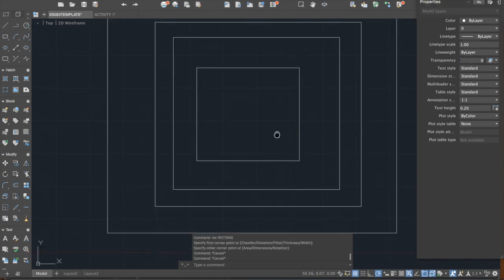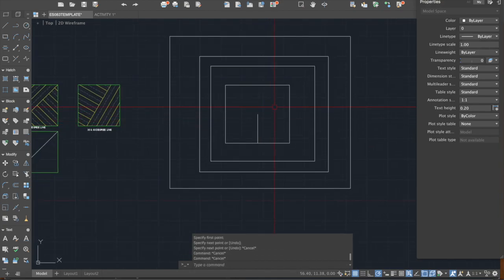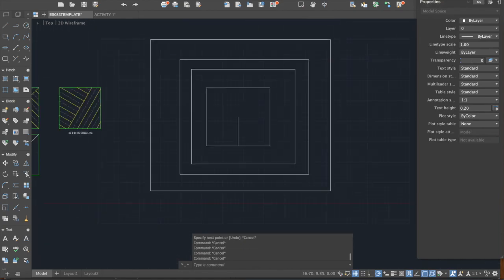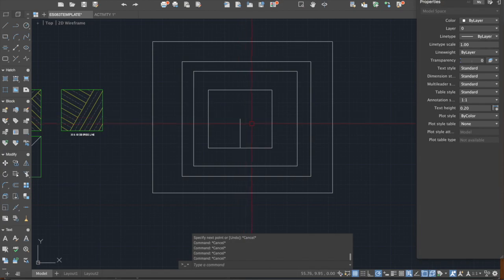So I will have a line here from the center towards this portion. Okay, so to discuss the first selection, which is to select borders or select boundaries, what you will do is, again, type the command, which is extend, EX, enter, and then it will ask for the boundaries. This time, instead of using this one, we can select up to this portion, meaning we wish to extend this line passing through these different borders because we wish to be using these borders or boundary.